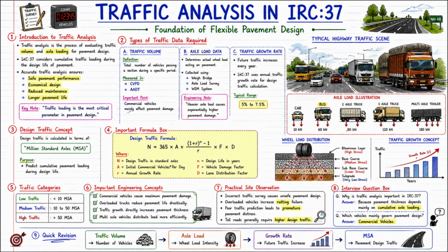Now look at the engineering note. Heavier axle load causes exponentially higher pavement damage. Now this is a very important practical concept. If the axle load increases even slightly, pavement damage can increase many times. This is the reason why overloaded trucks are considered the biggest enemies of highways.